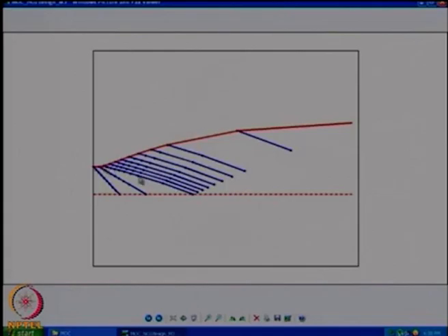From there I will get another characteristic, and now you can see that the gap between the characteristic lines is expanding very highly here. After it reflects on the symmetry line, you can think about this line going back out this way as a positive characteristic, and this line going out this way as another positive characteristic, and you can see that they are still expanding. These lines and these lines are still expanding out. Now after that you can again see this one is expanding a lot here, and when it goes out there it is still expanding.